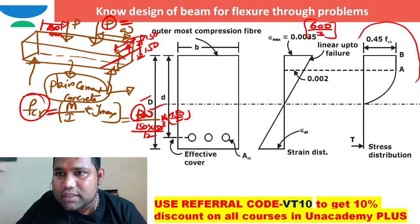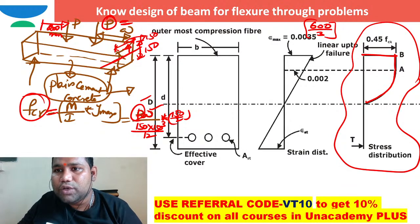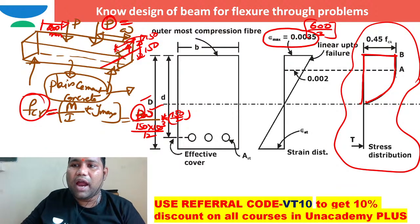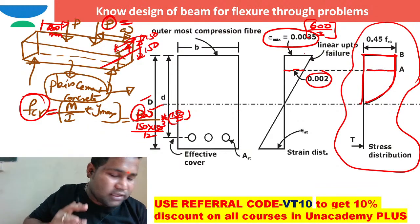Now the question is, sir, here you told us how the stress block is in this way. You need to answer why the distribution of the stress block is in this way. Some part is a rectangle portion, some part is a parabolic portion. You need to answer why the maximum strain in concrete in the compression fiber is taken as 0.0035, and why, at the point between the rectangular and parabolic variation, the strain in concrete is taken as 0.002. So there are four questions you need to answer.